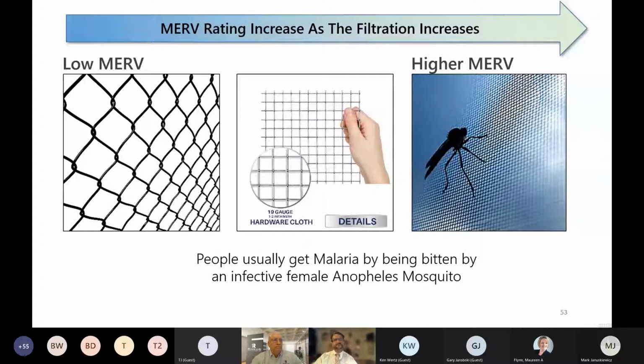And one thing about filters that I want you to understand is that with HEPA filters and many filters on the marketplace, they filter out essentially by straining, okay? So if you're trying to filter out mosquitoes and you have a chain link fence or even chicken wire, it's not going to cut it, right? But there's nothing that strains out the virus. The virus is too small to fit through. The virus will pass through virtually any filter, the virus particle itself.